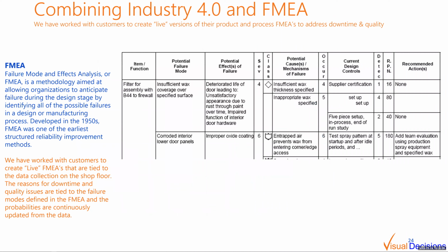Finally, failure mode and effect analysis, FMEA, is a very high-powered way within manufacturing to look at ways that the process can fail. And certainly variation is one of the ways that the process can fail when you have excess variation. And so what are the different failure modes? What are the effects of those failures? What are the potential causes of those failures and so forth? And then what can we do to both detect and prevent those failures from happening?